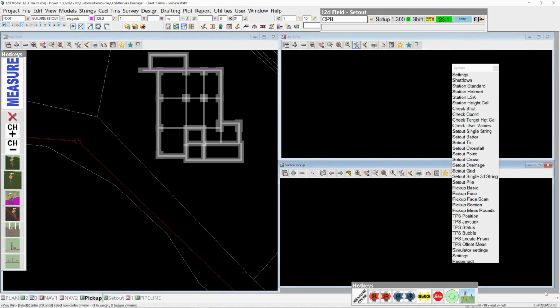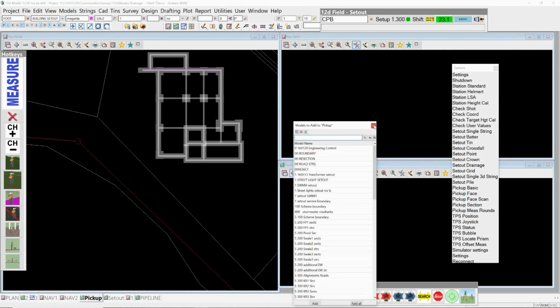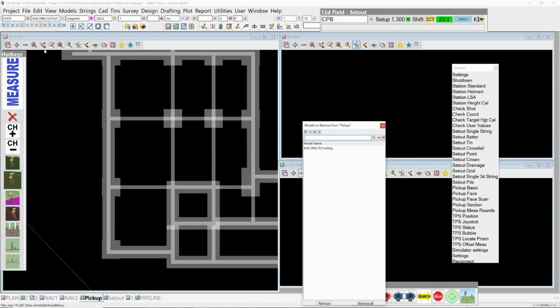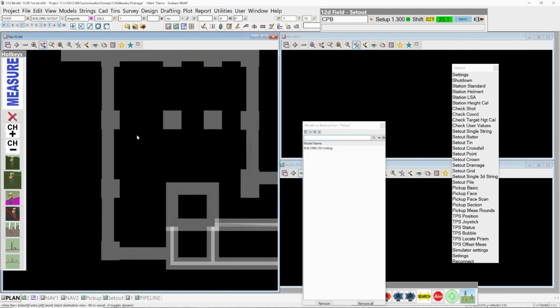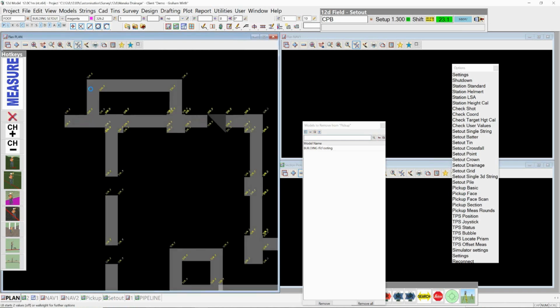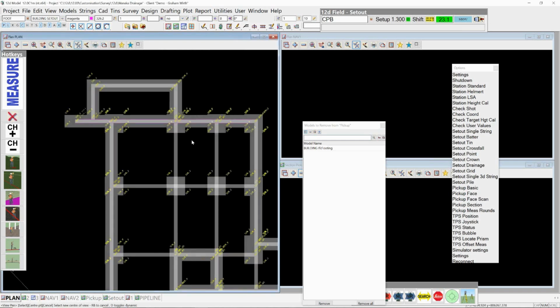So you've got the pickup here. I've got the strings turned on in this for the things. I've got the original footing that we brought in from the IFC as a solid. So in this area here, I'll just pan down to this footing. Once you've exploded the points in the tri-mesh, you can turn on such things as your Z values, which also aid you in picking different points for creating your strings.